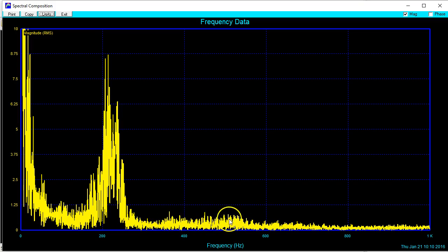It's very, very quiet. Now when you get above about 600 hertz, there's really not a lot of noise. It's really trickling off, right? So one of the things that I think we can take from this is that I expect there will be diminishing returns from increased sampling rates. We can already see the difference between 1 kilohertz sampling and 2 kilohertz sampling. 1 kilohertz sampling would get us up to about 500 hertz, and above 500 hertz there's not really very substantial signal energy.